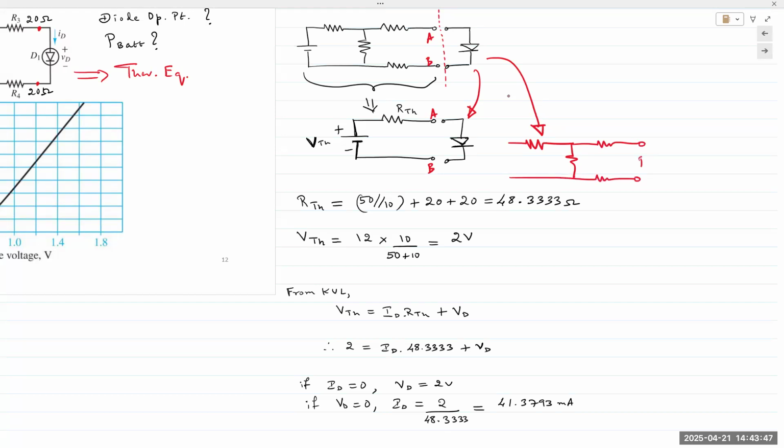What do we do with the voltage source? Anyone? We replace it with an open circuit. Well, we replace it, yes. I would say both answers are correct, but only halfway correct. So we don't short circuit. No need to laugh, it's just explanation. Yes, we place a short circuit, but we don't short circuit the source, and we replace the sources.